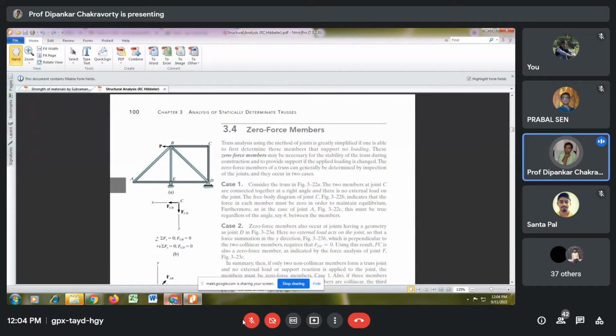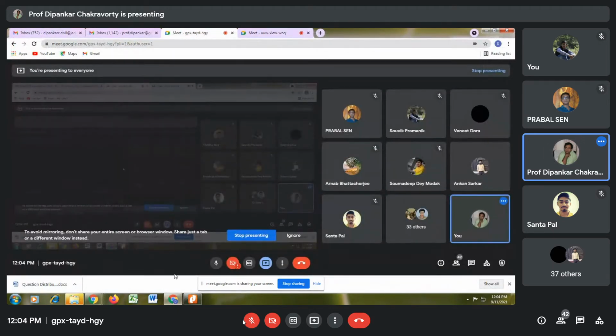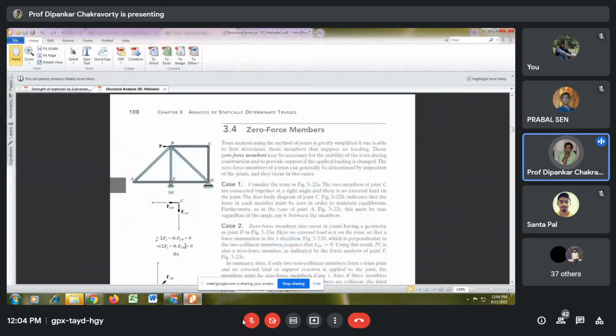Do you understand what I say? Once you have concluded that one member is a zero force member, then it is not there. Are you agreeable to me? Yes, sir. So now you tell me, among members EB and ED, is there any zero force member?